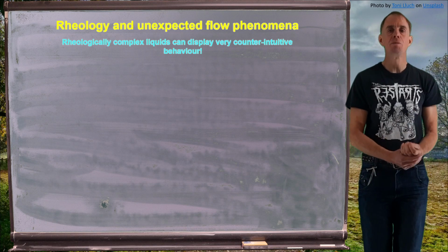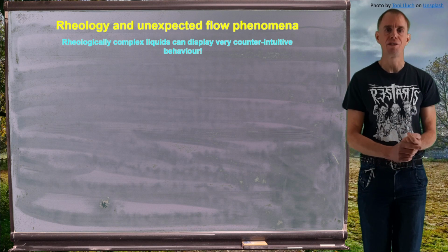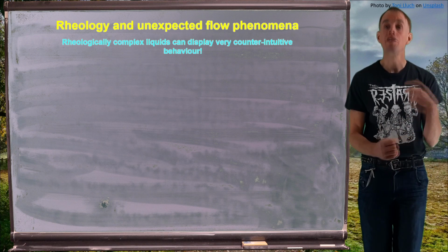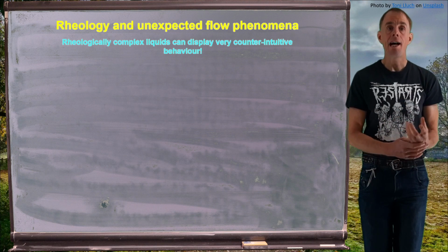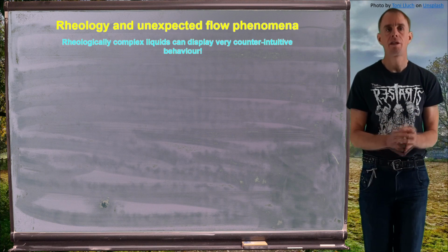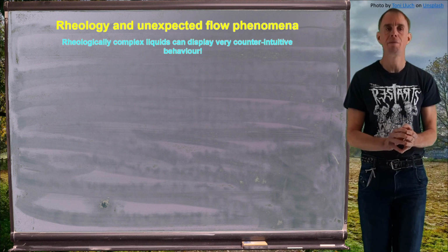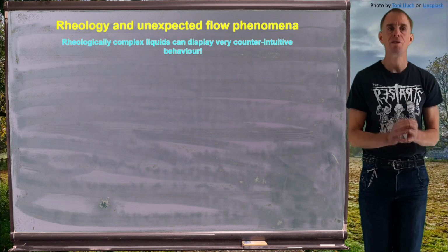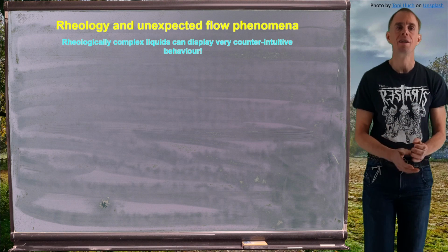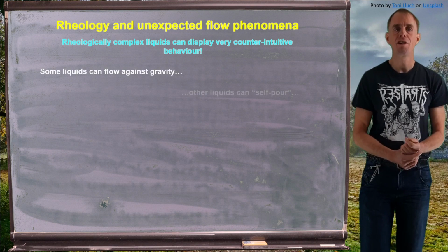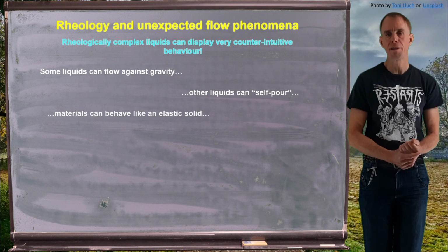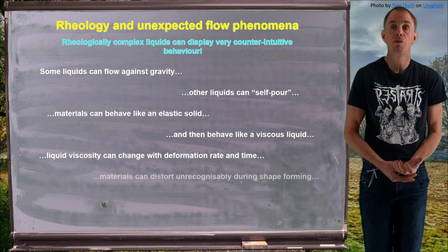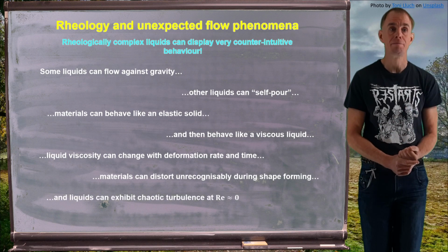So we're going to be dealing with some very, very interesting materials. We're going to have materials that have got properties of viscosity, properties of elasticity, sometimes properties of plasticity. And these complex liquids can display some very, very counterintuitive behavior. And one of the objects of this first lesson is to introduce you to some of this unexplained flow phenomena that you obtain. So, for example, some liquids can actually flow against gravity because of a build-up of stress in them, giving them enough body force to flow against the body forces imposed by gravity.